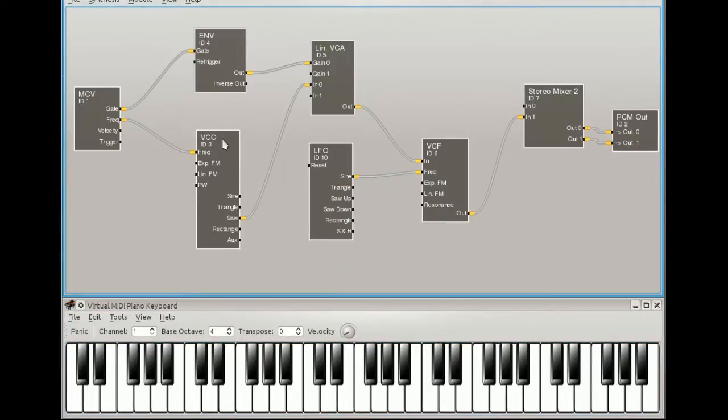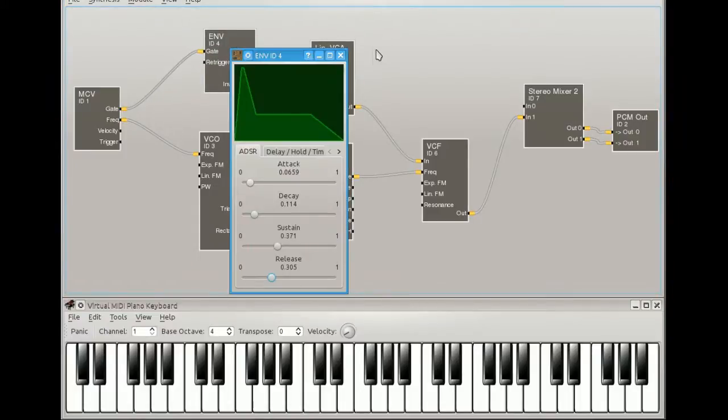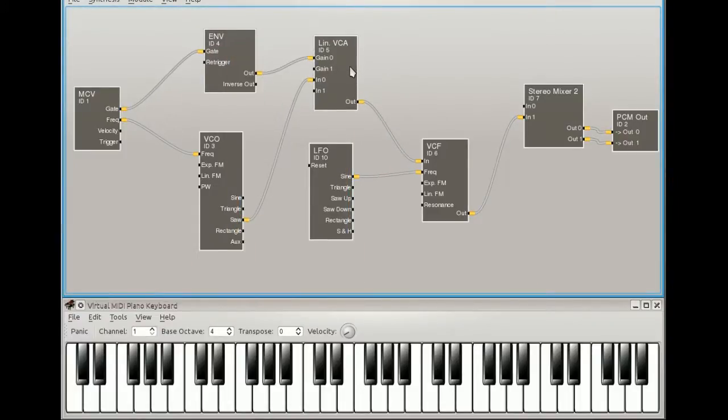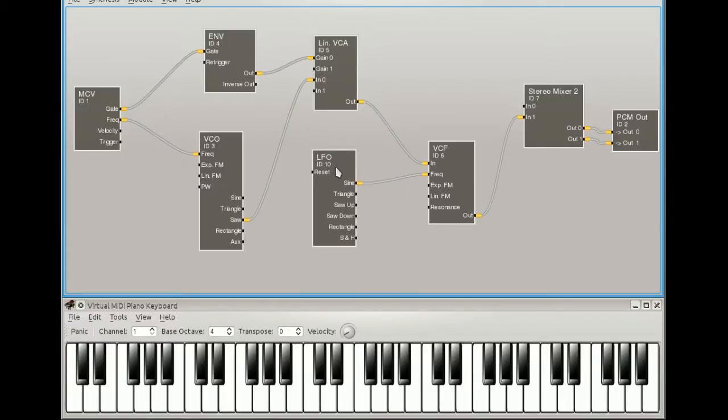So as you can see there, we've created some tones using an oscillator. We've used the envelope generator and the voltage controlled amplifier to actually shape that and control the note on, note off, so that we end up with an output which is tracking the keyboard. We've filtered that with a voltage control filter to give us the ability to change the timbre, and we used an LFO to add some modulation, in this case for the frequency, but LFOs can be used for all kinds of purposes. They can be used, for example, into another VCA to control amplitude, which could give us a tremolo